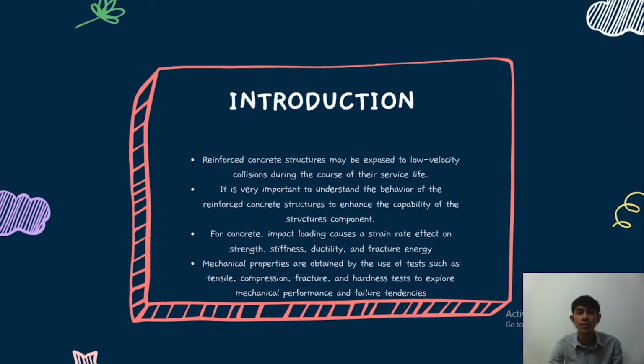Concrete's elasticity maintained virtually constant at low strains, but when cracks form, it begins to diminish. Because concrete does have a low coefficient of thermal expansion, it shrinks as it ages. Due to shrinking and strain, all concrete construction will fracture to some extent. Concrete that has been exposed to long-term stresses is susceptible to creep.